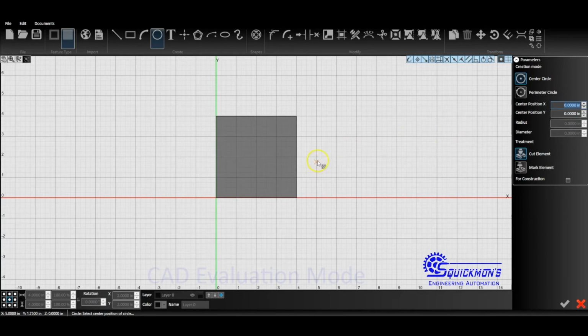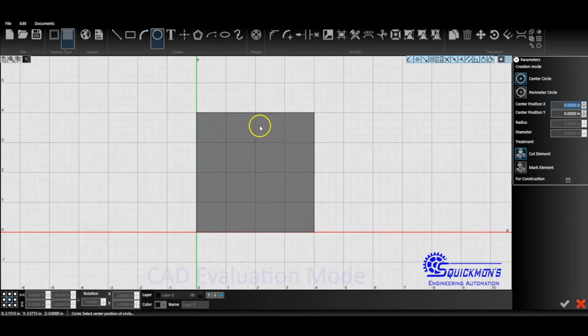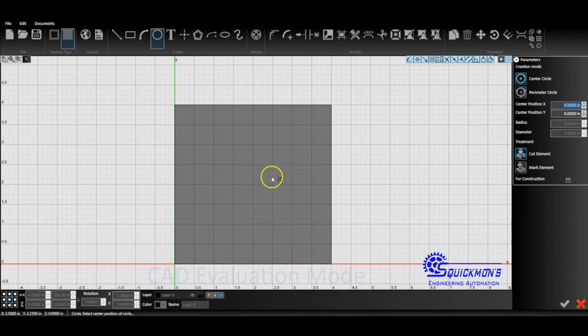So now I'm going to zoom in to this part, and we're going to use the rulers on the sidebar and the bottom bar to know where we're placing this first circle. So we're going to go ahead and drop it right here. Now notice as we zoom in, we get some different major grid lines, and it continues to break up our minor grid lines into major ones as we zoom in further. So whereas before we had a length of measure for major grid lines of 1 inch, now we have major grid lines a ½ inch from each other.